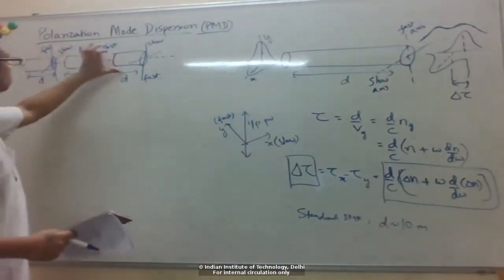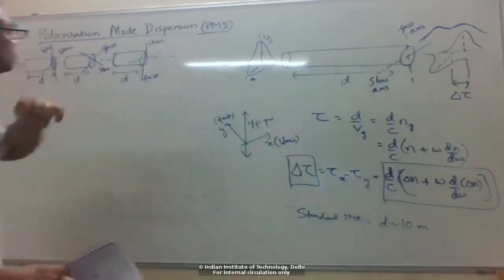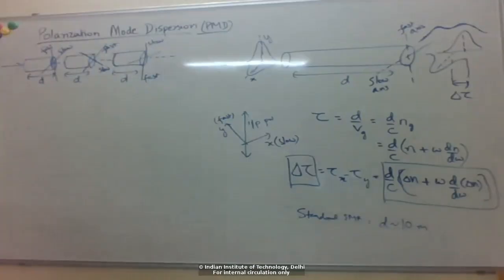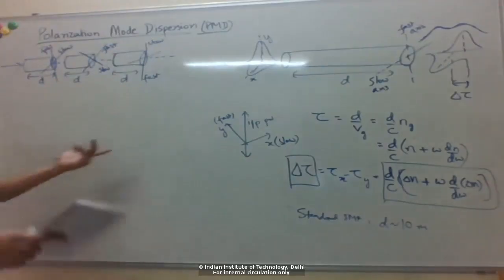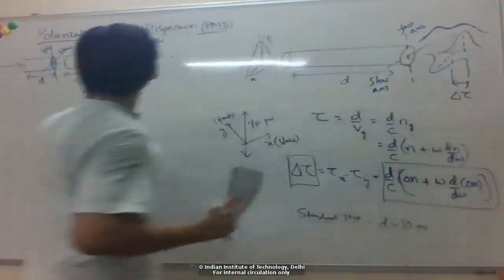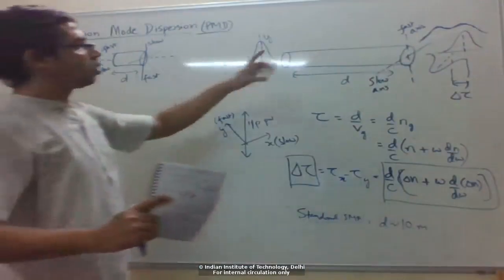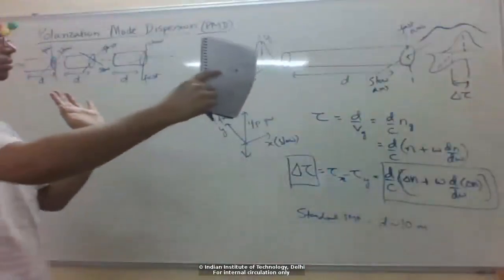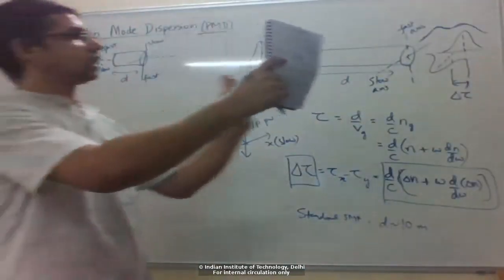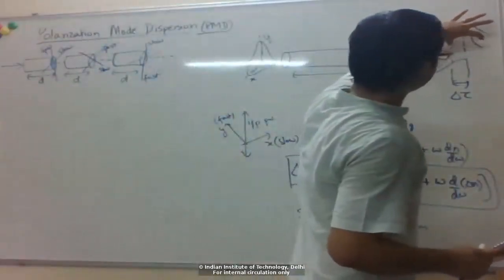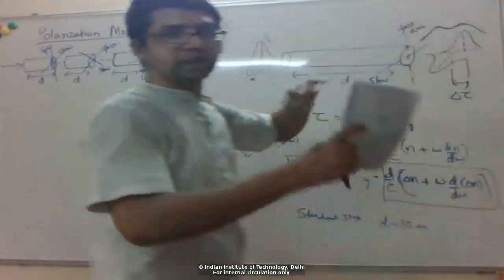Basically the birefringence axis is randomly changing due to the random nature of the stress. So now you can imagine what's happening, right? For each segment you get some lag between the polarization components. For the next segment, you have to project the powers along the new axes, and treat them as independent components, which again acquire some lag. That could increase the broadening further, or it could actually make them come back together a little bit.